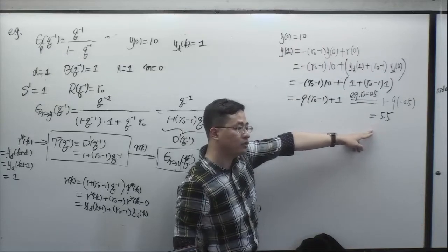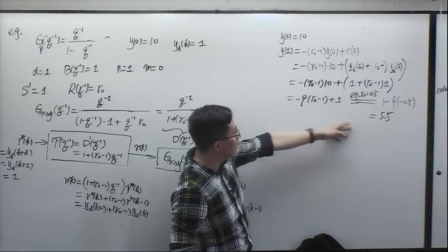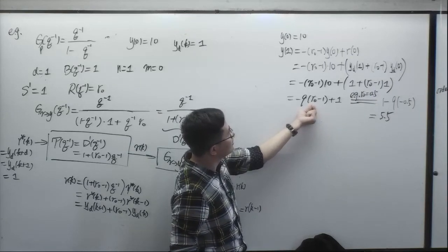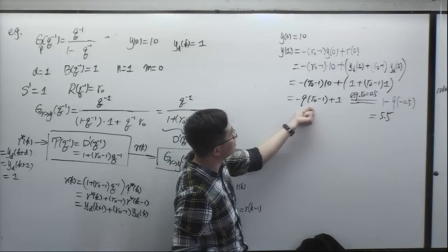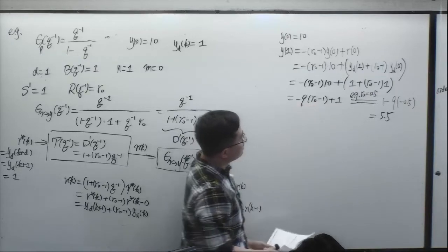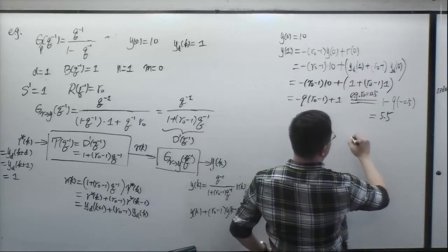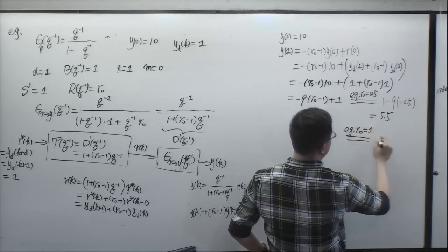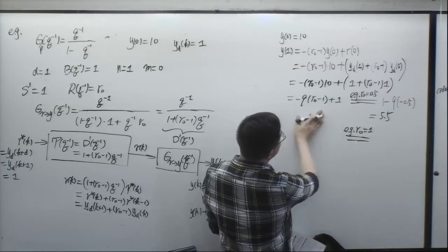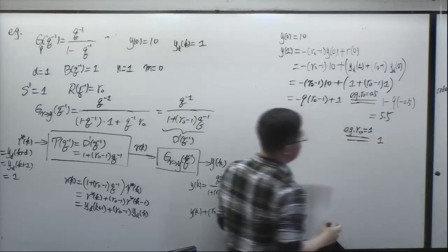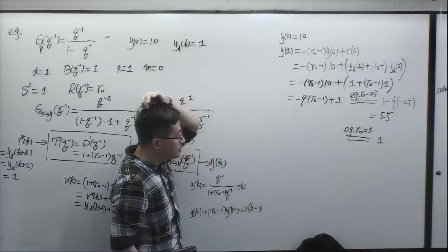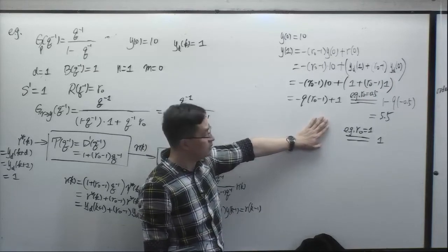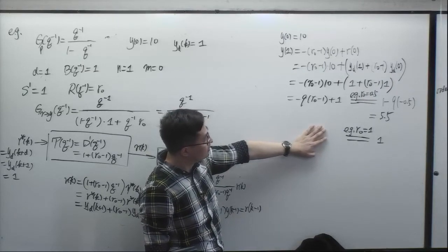And what is the extreme convergence speed? How can we design, what kind of boundary values can we choose for R0 to make the convergence as fast as possible? Right, if we design the closed loop pole to be 0, then we can have the convergence to be 1. One-step convergence. All right?